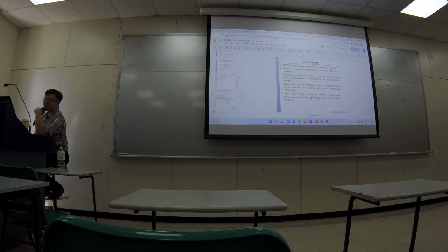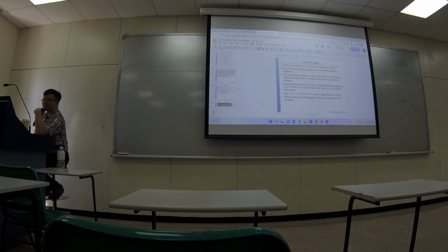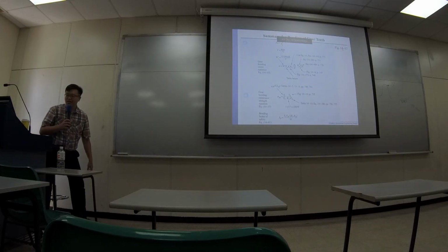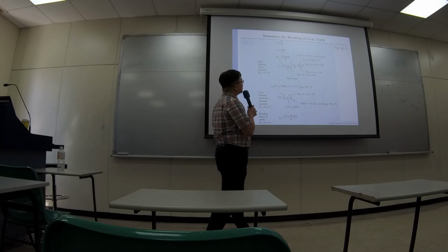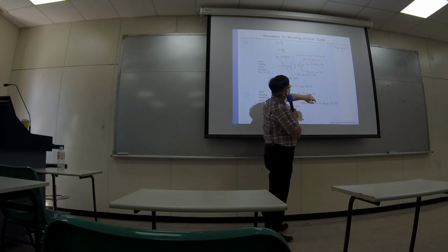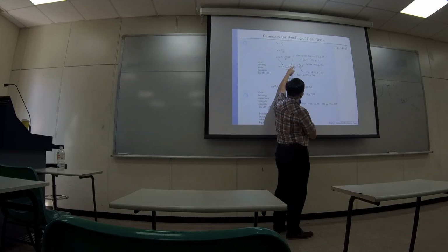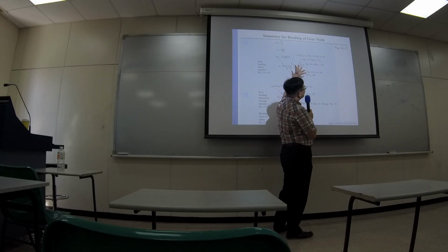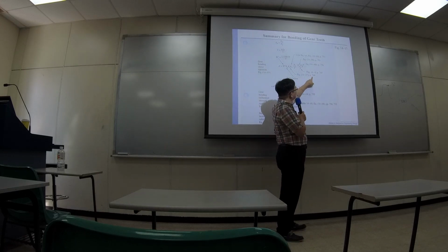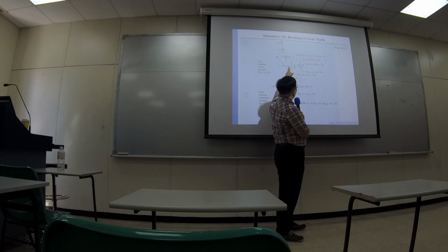The entire chapter of this book is trying to explain all kinds of factors. But I'm going to show you bending, yes. So at the end, the stress can be computed by W times the Ks, 5 Ks, times P, capital PD, this is the diametral pitch, F at the bottom, and some parameter J. This book even tells you which page to turn to in order to figure out how to compute each K.